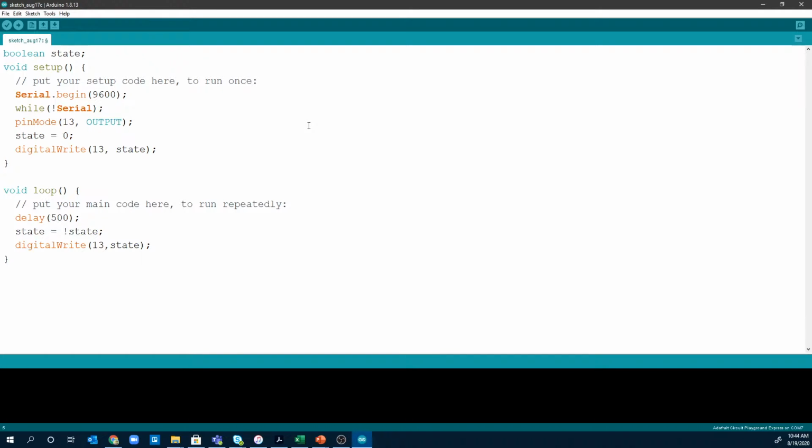This is not required for all Arduinos that you do this. However, it will work on all Arduinos. So in other words, things like the Arduino Uno or Duo, those don't actually require you to make sure that the serial port is there. It will simply hold the data until the port exists. However, on boards like the Circuit Playground Express and some of the Arduino makers and most of the 32-bit boards, honestly, if you haven't activated the serial port and made sure that it's there, you're going to lose data if you try to write to serial before it begins.